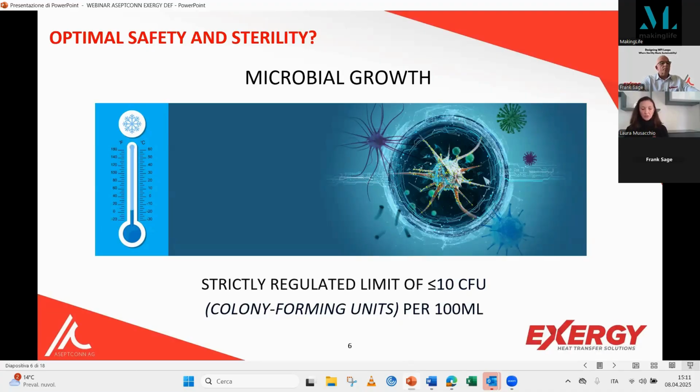When the temperature is maintained above 71 degrees, more or less, virtually all pathogens are dead in 30 minutes, including critical bacteria, toxins and parasites, for example Cryptosporidium or Giardia, and at 85 degrees, all these types of pathogens are dead in a very few minutes.